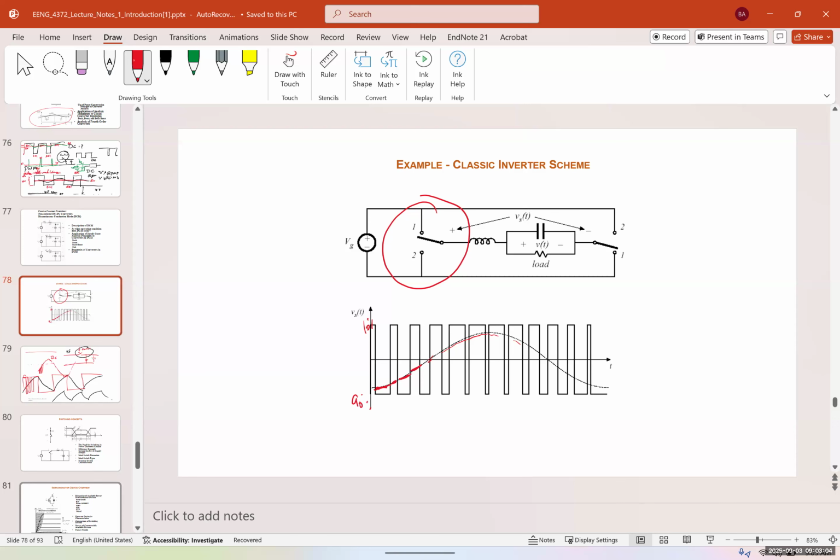And they're much bigger, like 5-6 times the size, because they require a lot of filtering, sophisticated control system, and so on. So we can create AC signal from DC using switching. And depending on how sophisticated our switching system is, we can have a very good DC to DC or a very good DC to AC.